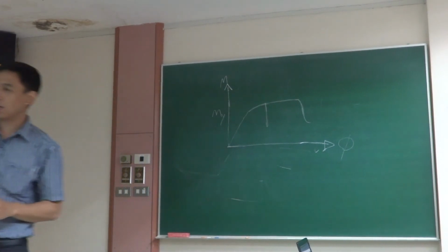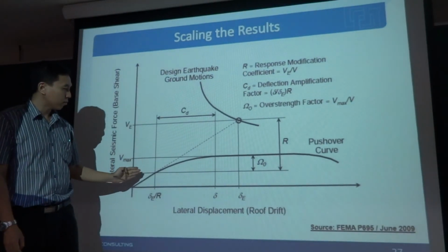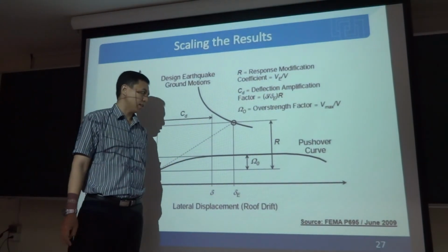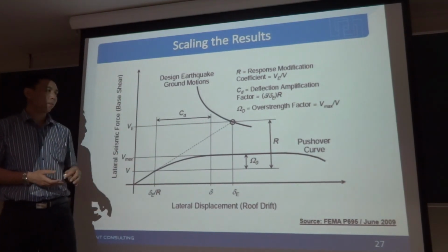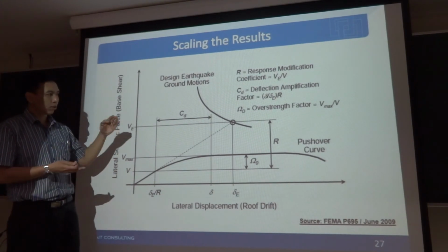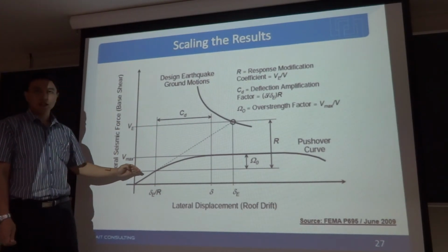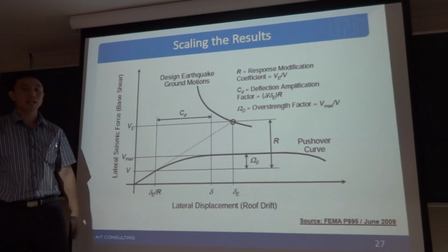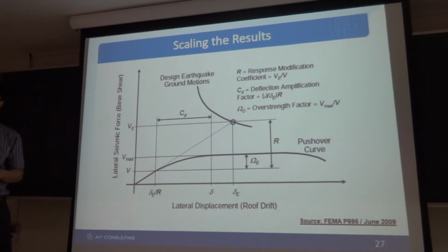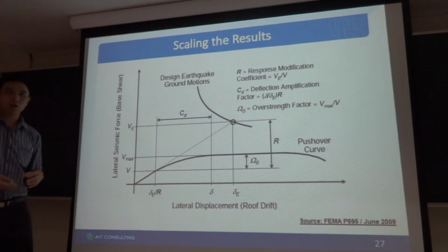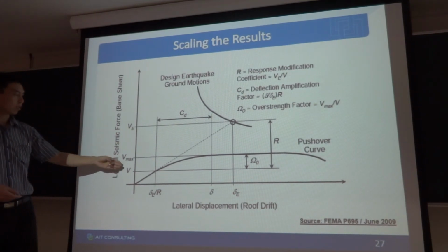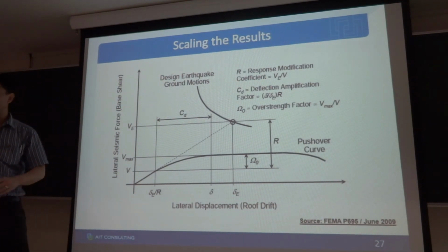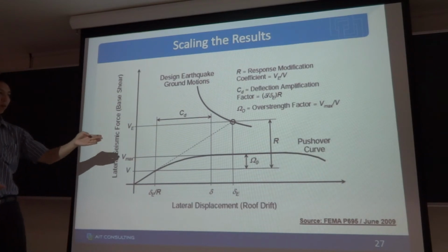So this is the seismic design procedure. Our members should have large deformation capacity. To get that, we have to provide proper detailing, and the code allows us to reduce the seismic design forces by a larger R value. If you have brittle elements, a brittle structural system with less redundancy, only the core wall, the code will not allow reduction as much as for a special moment resisting frame. So the R factor for the bearing wall will be 4.5.